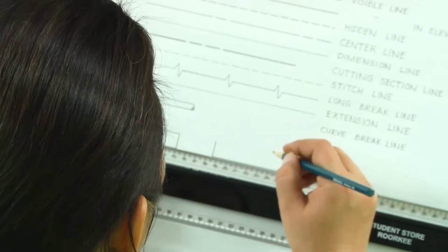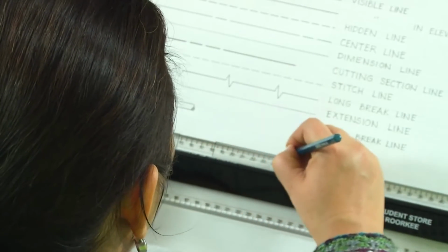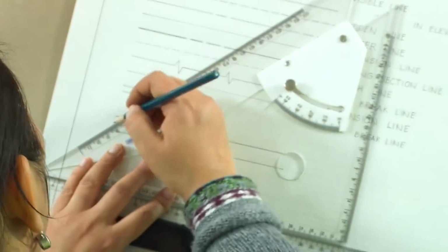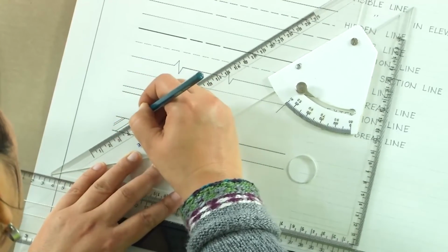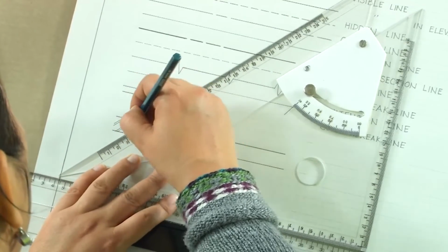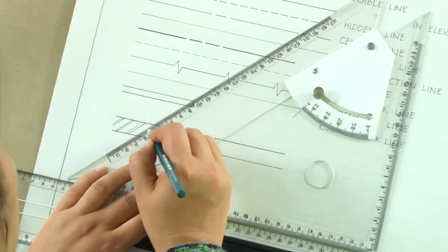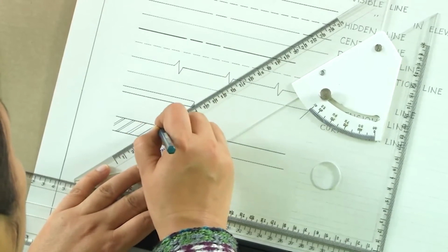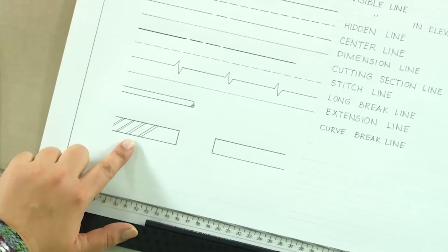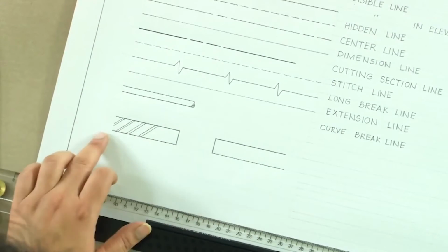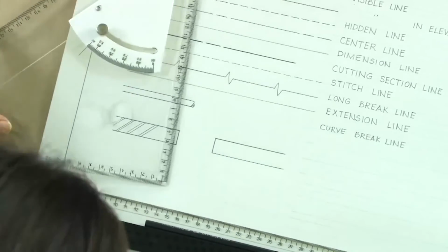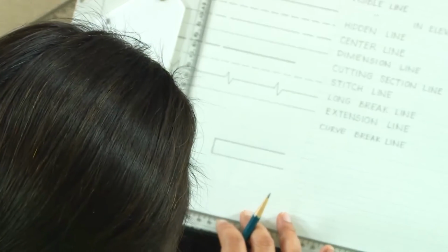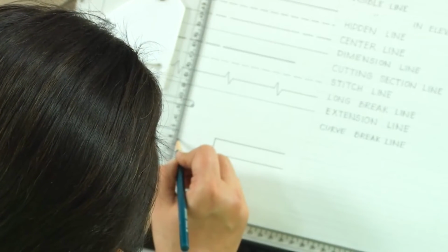So, if the wall is say 230 mm thick, and it is a brick wall, we will have a hatch which will be representing the brick wall. You can complete this section in this manner. So, this is the brick wall with the brick hatch represented here. Now this entire thing has to be on a certain scale.